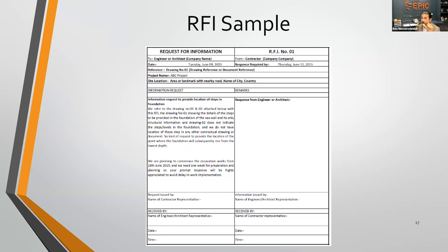So the question may be posed here: what would you like us to do between this discrepancy? Which one's accurate? If the architect or the owner comes back and says, I want the gold leaf, and the paper trail all adds up showing that the contractor only bid on the wallpaper and it's a valid change order, then this RFI would be turned into a change order for the delta, the price difference between the typical wallpaper and the gold leaf.